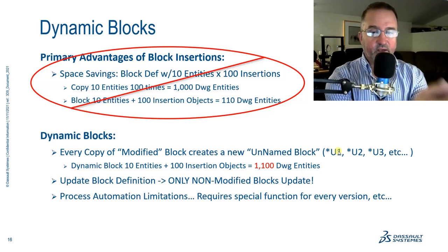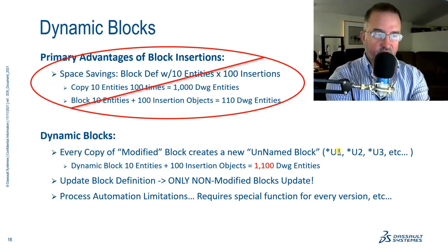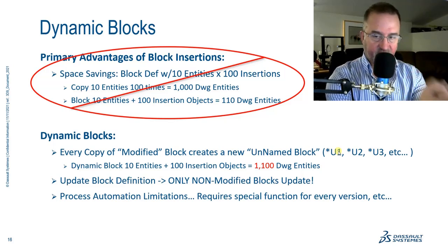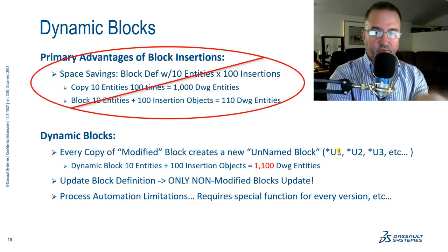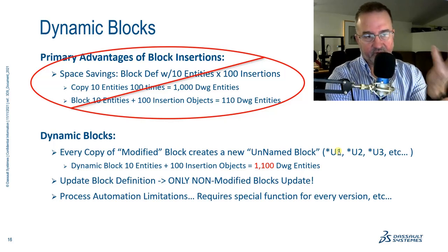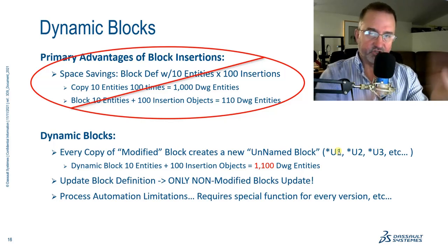Now, if dynamic blocks are involved, the only way to do that through a highly sophisticated automated fashion is to write a specific program for every single block that you have in the drawing. And it is extremely tedious to try to dig multiple levels down to discover what is the actual name of the parent, because in a sense we have a parent block, and then all these other variations are all children.